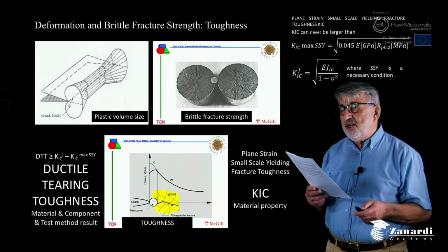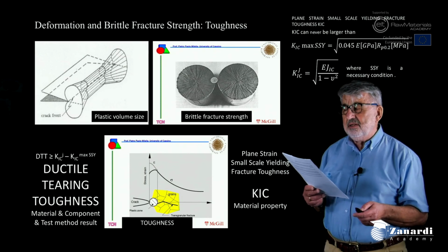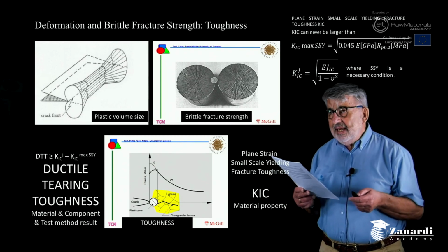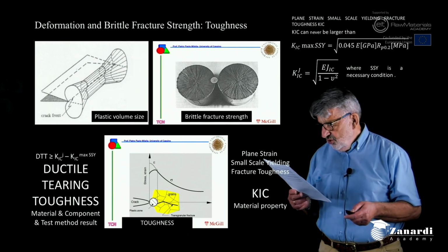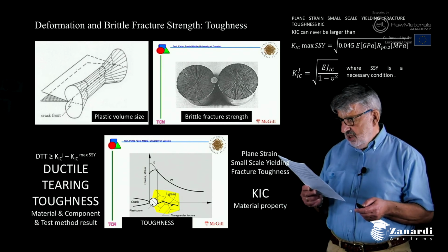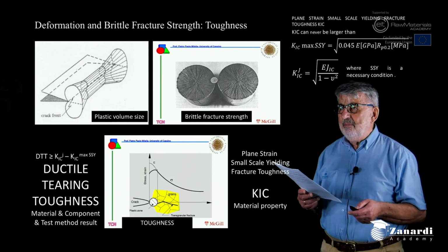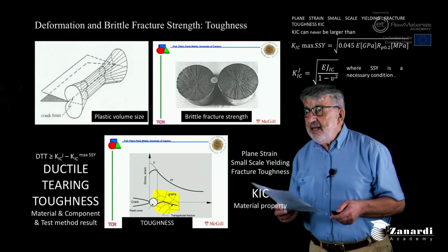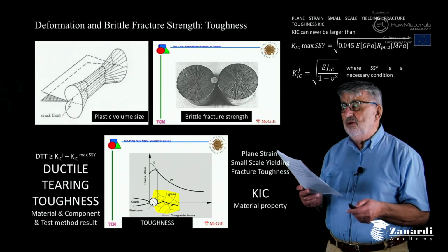But this direct measurement of K1C is possible only for fully pearlitic ductile irons, that is on average 30 megapascal square root of meter, and high strength conventional ADI, for example ADI 1200 megapascal ultimate tensile strength, which shows a K1C of about 81 megapascal square root of a meter.